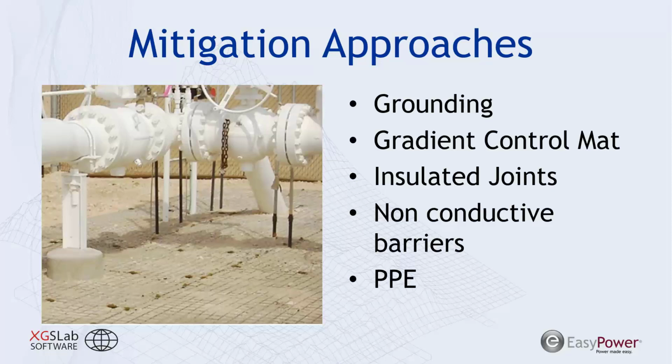Now, a lot of these are different mitigation options. Many of them are not applicable for all situations. You're limited by the operational practices or what's allowed by the recipient or what's allowed by the transmission line. And you may not have complete adherence implementing something like PPE, especially if it's one pump station where they need to wear electrical gloves and every other pump station they do not. It's important to think of those real-world practices and incorporate that into any sort of mitigation design.